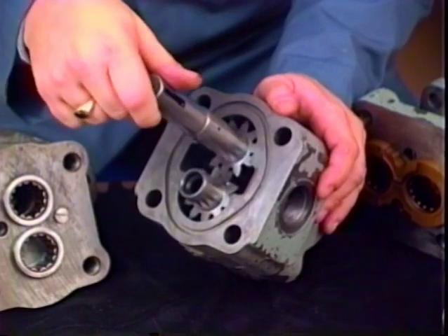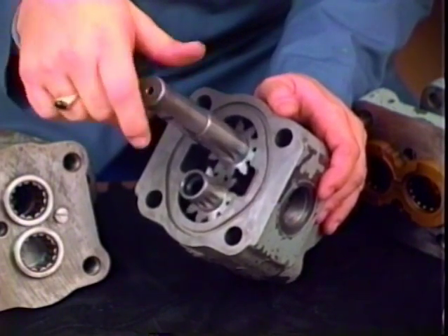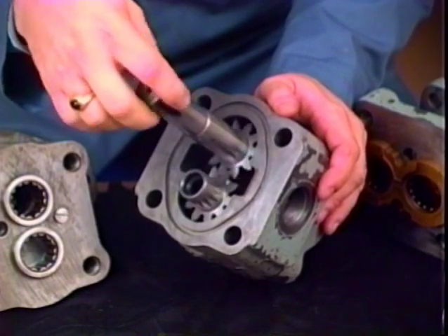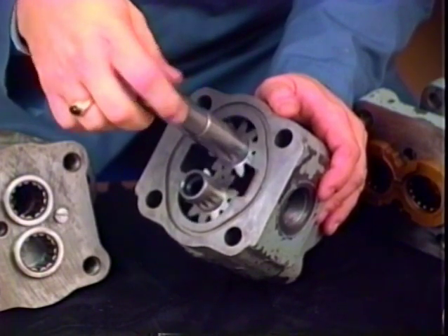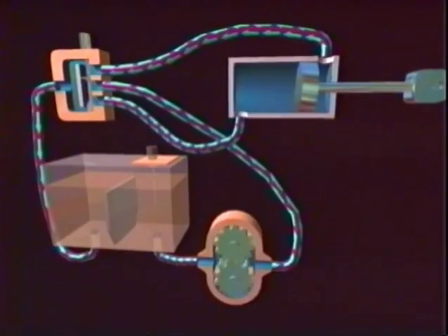Earlier in the video, you saw that a hydraulic pump is kind of like the sorcerer's apprentice. Unless the operator shuts it off, it keeps on pumping, regardless of the system pressure. Think for a moment about what this means. What would happen if the operator forgot to return the control valve to the neutral position after the piston rod was fully extended or retracted? Unless the pump were turned off, the pressure would build up until something broke.